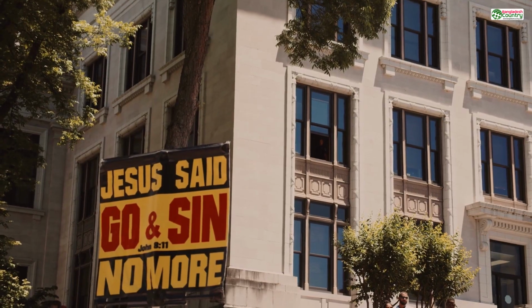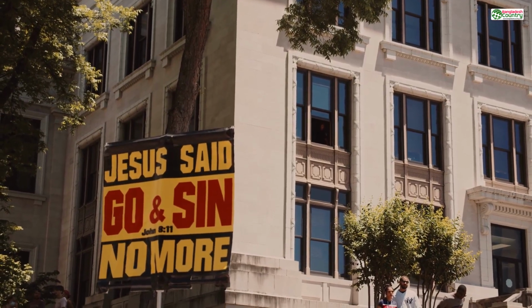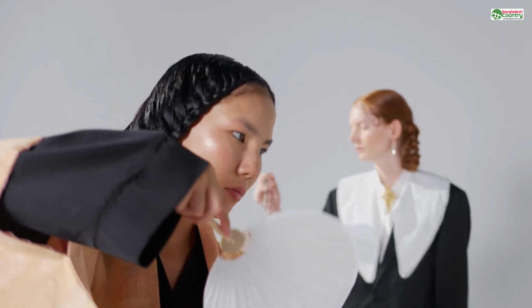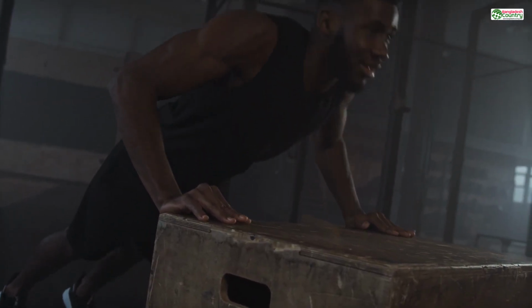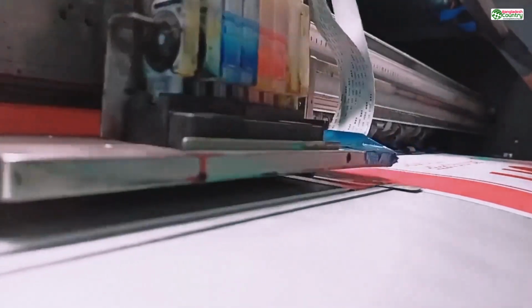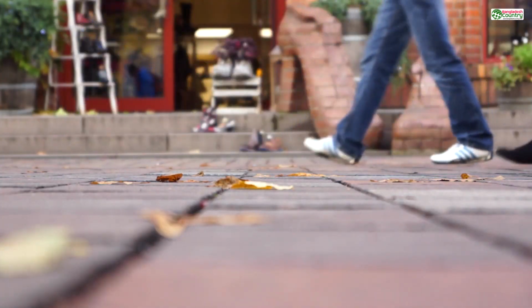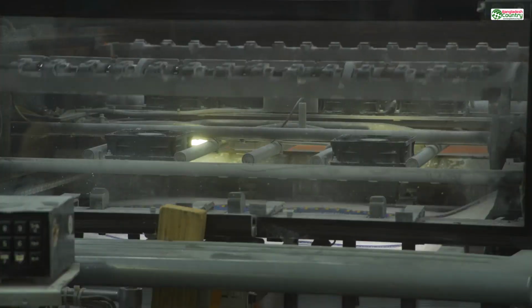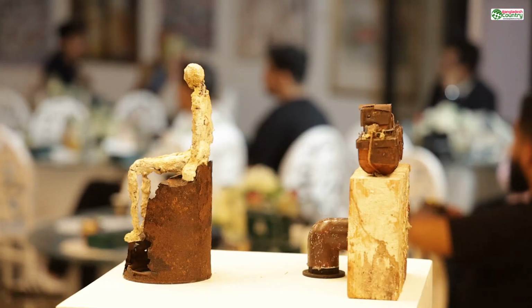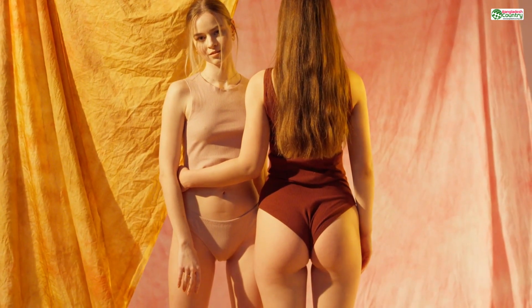Another, more sinister version of this problem is internal geometry. Let's say you're designing a coffee mug. You model the outside shape, then you model the inside shape as a separate piece and just push it into the first one. On your screen it looks perfect. But to the printing software, you've just created chaos. You have two different surfaces occupying the same space, and the software has no idea which one is the real surface. Do I print the outside? The inside? Both? It's like giving a builder two different blueprints for the same wall, and telling him to figure it out. The result is confusion and failure. Your model must be one single, unified shell.